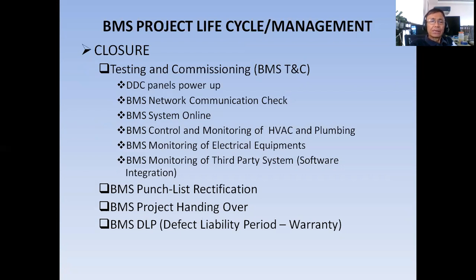Once your DDC panels are all powered up, then one by one, you can connect the BMS network cable. In this part, you should be very careful. Make sure there will be no power going to your network communication, because if there is power going to it, let's say even 24 volts, it will damage all your DDC controllers. That is a big catastrophe, so you have to put that in mind.